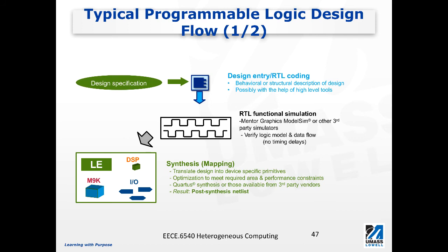It will map these specific functions onto the hardware resources available in this particular chip. During this stage, optimization will be applied to meet the required performance constraint. And the result is a post-synthesis netlist.